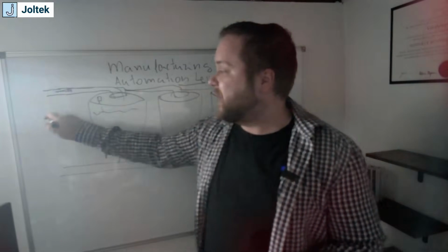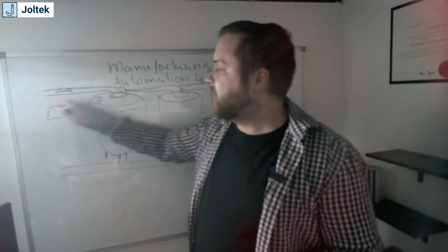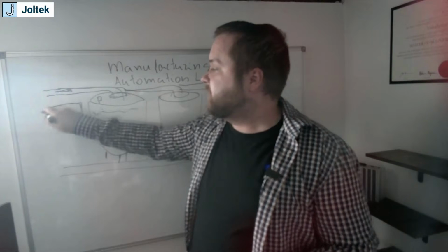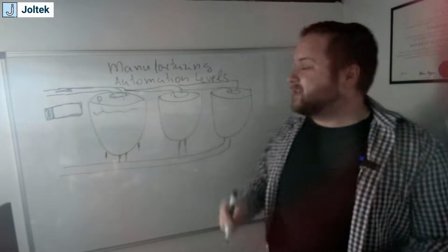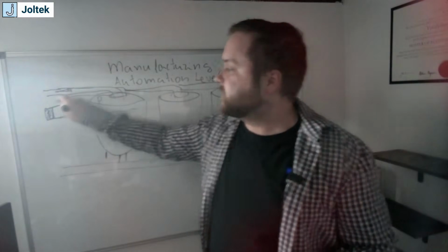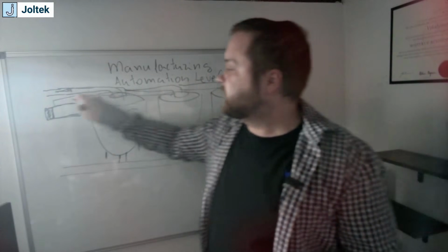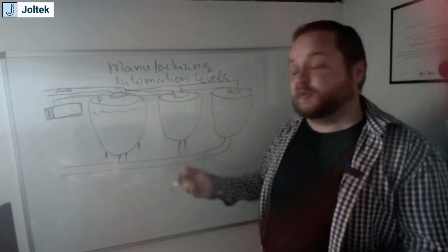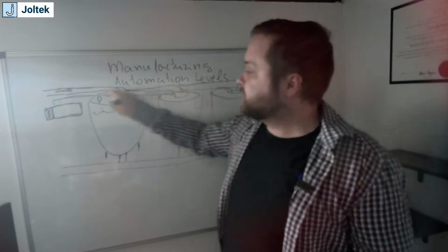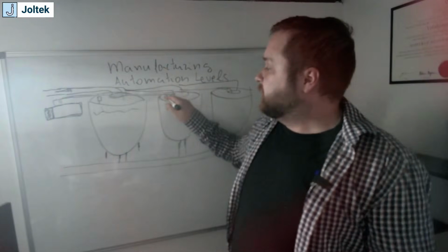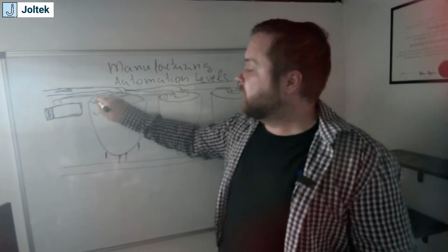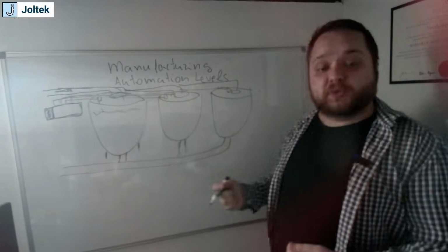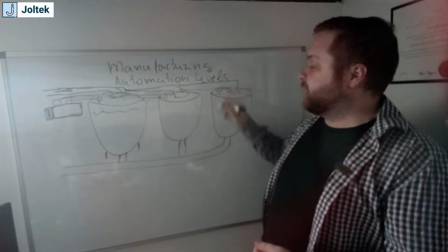So now you have a panel where you have a PLC rack, and again, I'm going to draw this a little bit crudely, but you ultimately have a PLC that will be processing various signals, right? So you have a signal coming from this valve, and when I say from, it's tied to the PLC, but obviously it's an output to open the valve. And then there are different sensors here. Here you have, again, a level sensor. A lot of times that's going to be analog, so that's going to be going into an analog input card on the PLC side. Once again, you have a third sensor.